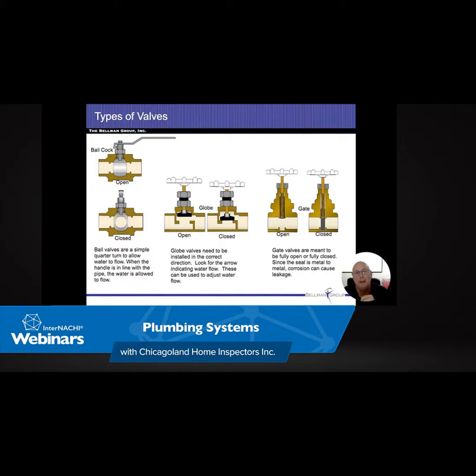Backflow valves, this drawing, and I think the picture on the next slide, are from areas of warmer climates, all right? I'm not an expert in Arizona or Texas and stuff like that, but I don't believe they go as deep with their sewer lines as we do. I think it's on the shallow run, so it's easier for them to fix things if they can get to them. But even with water or waste lines, there's been, I want to say it was like the 70s or 80s, we had a whole bunch of flooding up in this area, and a lot of plumbing companies, when the sewers would back up into the houses, they would sell these backflow prevention things.